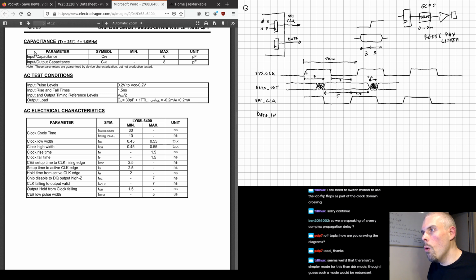All the values in the data sheet are relative to the SPI clock that it sees itself. So you have a dual layer, because the phase of that clock depends on that delay, and that's the only edge we can reference input timing to. So 1 nanosecond after, the data becomes invalid.